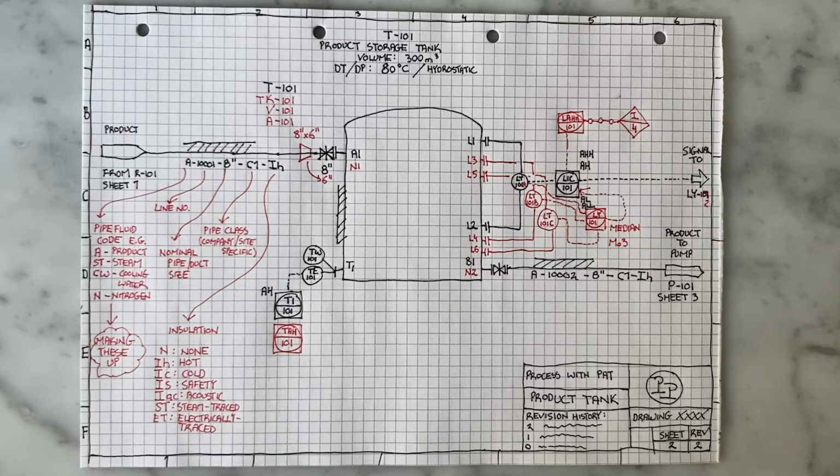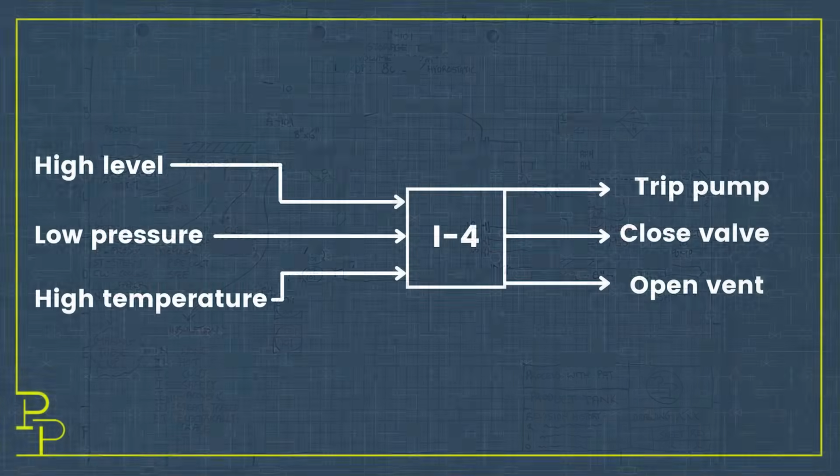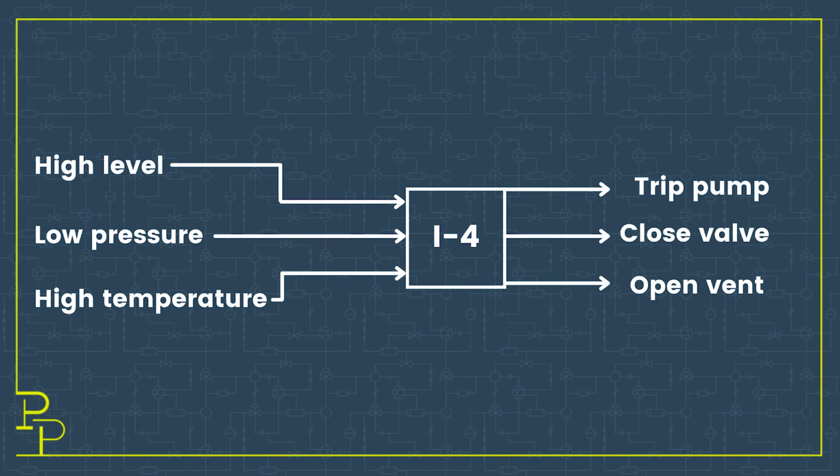You will also find labels such as ESD in blocks like this instead, which means emergency shutdown. The 4 designates that very specific actions decided up front will happen if interlock 4 is activated. We create dedicated drawings called cause and effect diagrams that would describe everything that would activate interlock 4, so those are causes, as well as what interlock 4 does. Those are effects.